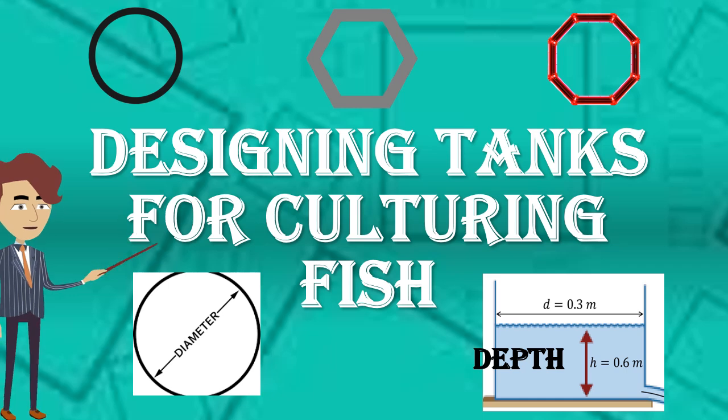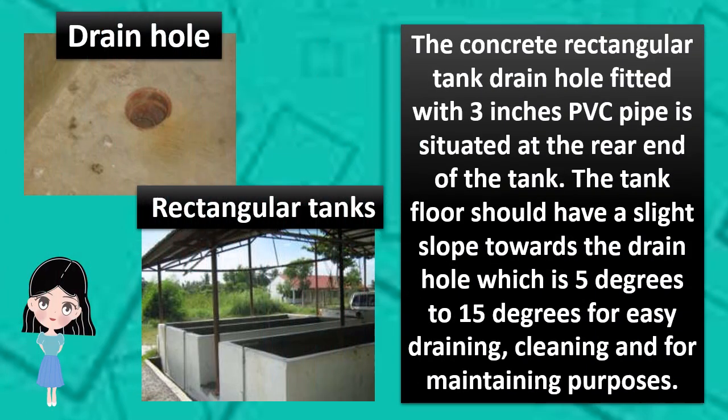Tanks for grow-out are typically 4 to 10 meters in diameter and 1 to 3 meters deep. In the concrete rectangular tank, the drain hole fitted with a 3 inch PVC pipe is situated at the rear end of the tank. The tank floor should have a slight slope towards the drain hole, which is 5 degrees to 15 degrees, for easy draining, cleaning, and maintenance.